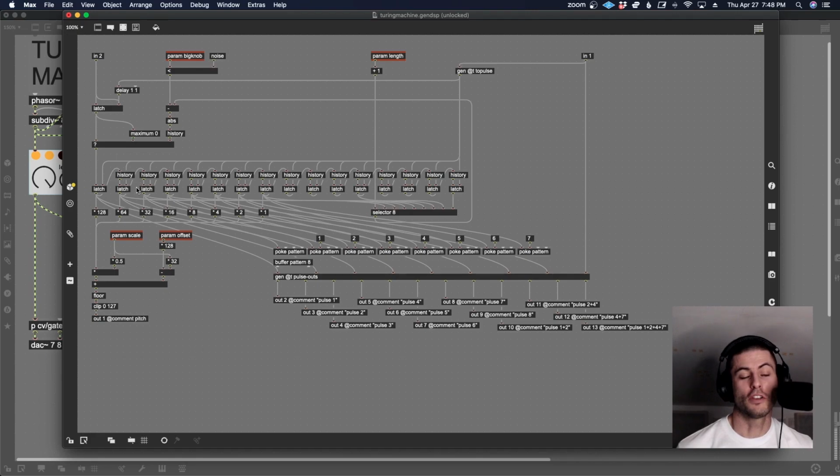We have a bunch of bits, zeros and ones, coming out of each of these. And by scaling those different bits and adding them together, we're turning that into some number between 0 and 255, which is pretty much what a digital to analog converter does. It just takes a bunch of bits and turns them into a voltage.